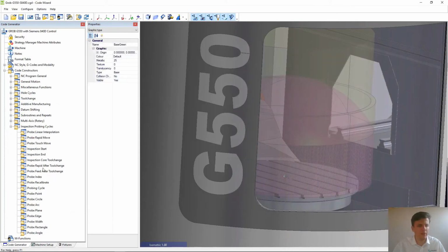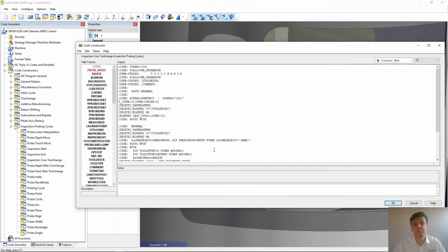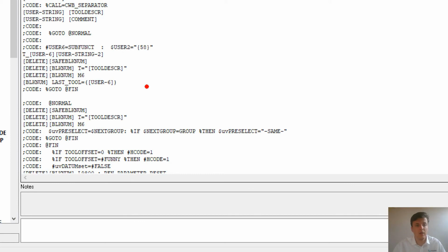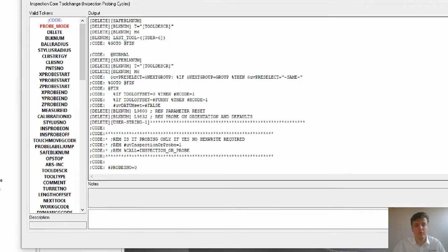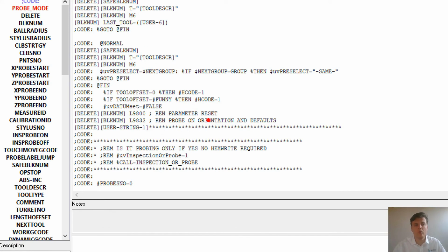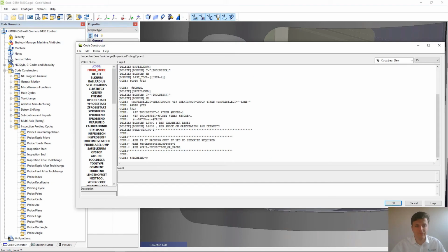Well, I think you have an extra thing you need in the core tool change. Don't forget to activate your probe. So I'm using the Renishaw installed macro to activate the probe and also orientate the probe, so I always touch with the same surface.